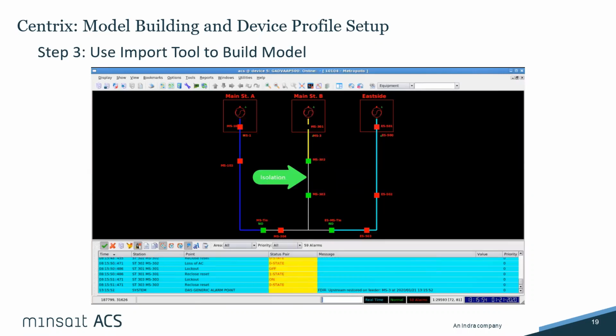We're going to do the upstream restoration, and then now we're to a point where we have to decide which feeder, either on either side of it, has the most capacity. Once we run those load flow analysis and the various FLISR algorithms, we will then restore using the best possible source. And there we've completed our downstream restoration process.